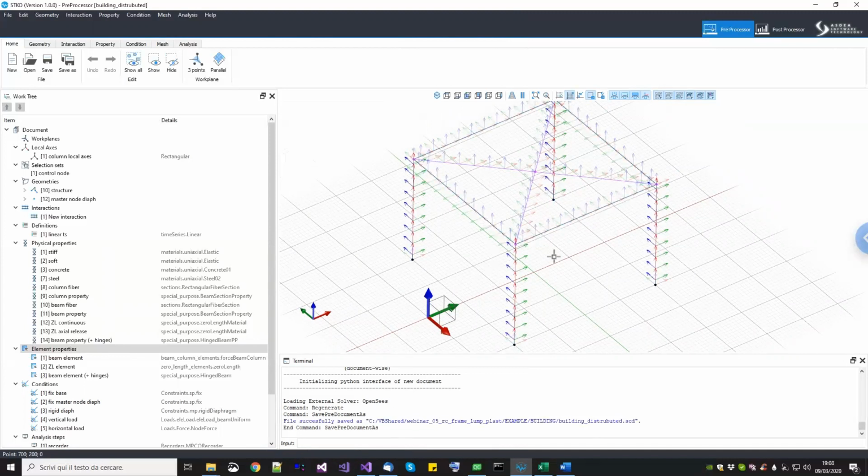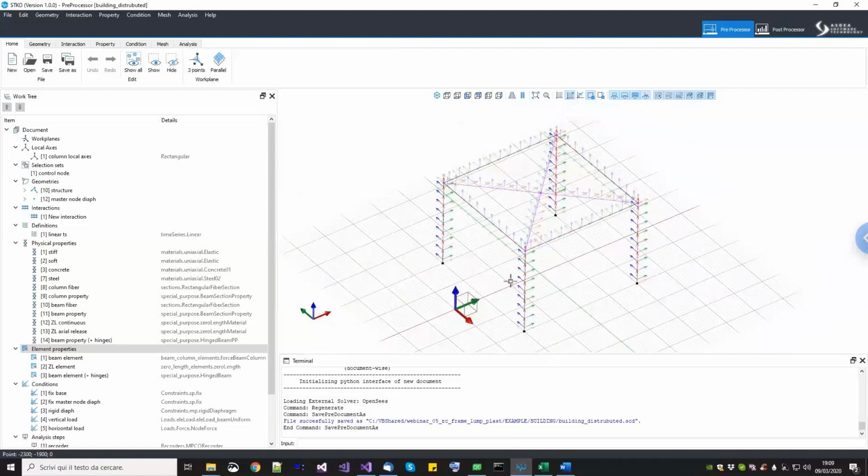the beam column joints, because in those examples, the shear failure was dominating the bending failure, and the joint failure was dominating the shear failure. Now in this example, we are focusing on the bending failure. That's why we want to see it. So we do not include any shear or joint failure. Okay, so just the frame model we did in the previous webinar.